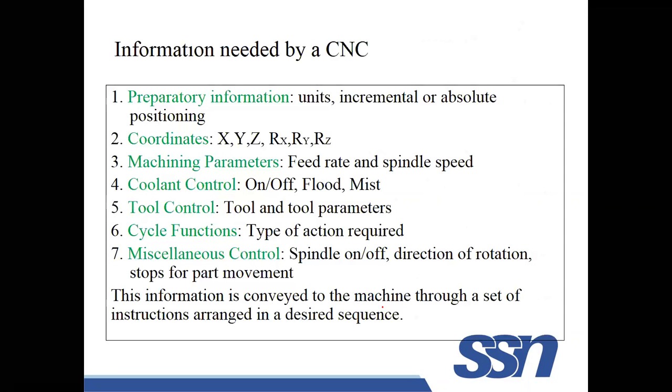Here, information needed. What is all the information needed for a CNC machine tool? First one is preparatory functions. These cover what units we are going to use. Unit in the sense whether metric or inches. Metric in the sense you will be writing mm. Inches means the length will be measured in inches. Okay, so these are the values.